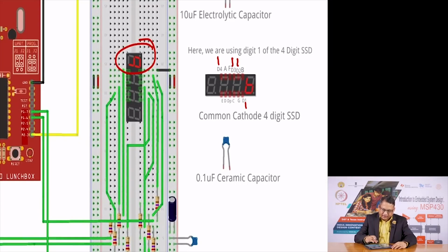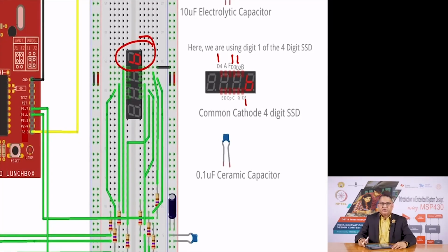We are going to connect all the 8 segments A through D, P, and then we are going to only use one of the digit common pins as we see in here. It does not matter which one you use, you can use first digit or the second digit. All you have to do is ground that digit common signal.